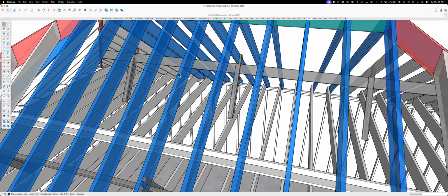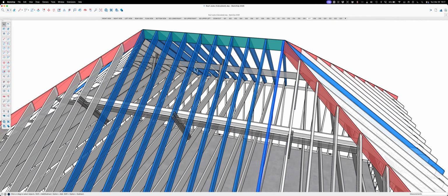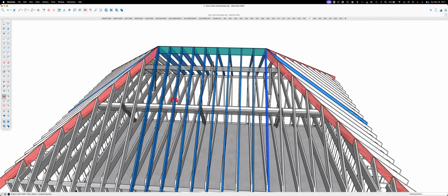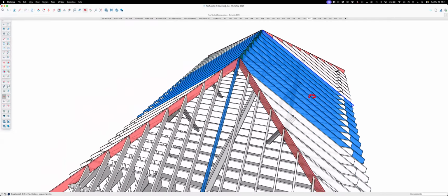And you just do that about every 8 feet, I think. They wanted us every 8 feet or less. So I'm sure there's a code for that. I just remember doing it like that. And up here, everybody wants to do trusses, so we haven't done purlins in a long time.